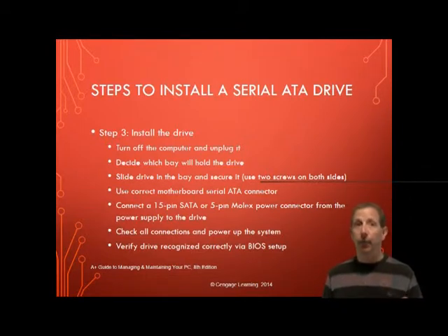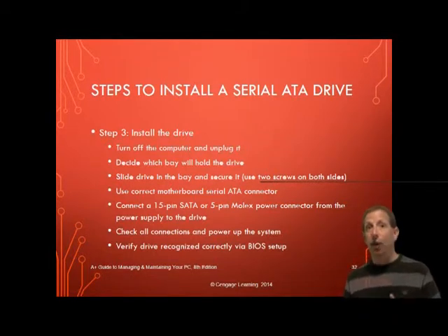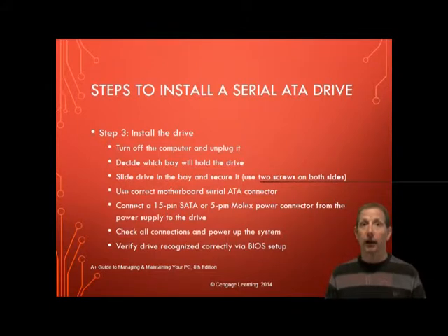Also, some bays are wider than others to accommodate wide drives such as a DVD drive. Now, will the data cable reach the drives and the motherboard connector? If not, rearrange your plan for locating the drive in the bay, or purchase a custom length data cable. Some bays are stationary, meaning the drive is installed inside the bay because it stays in the case. Other bays are removable. You remove the bay and install the drive in the bay, and then you return the bay back to the case.